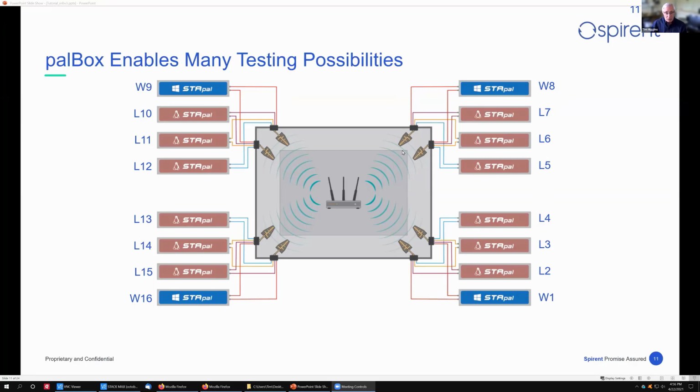So we'll come back and look at this to see what part of this we're going to use in a second. Oh, and by the way, not shown in this diagram are the attenuators between the groups of 4. There's an attenuator channel behind each of these antennas, so each of the groups of 4 can be set at a different distance and have a different path loss introduced. So you can play with that. It's another factor in the test.